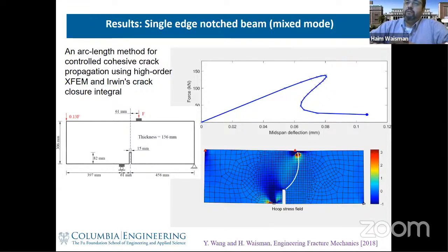Because in the isotropic problem, basically one has to satisfy the Neumann condition at the crack tip. But isotropic degradation basically knocks down the diffusion in all directions, which is not satisfying the Neumann boundary condition, right?